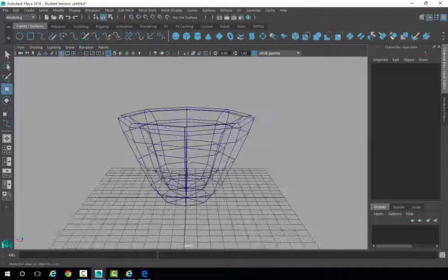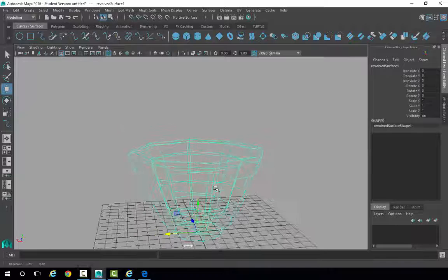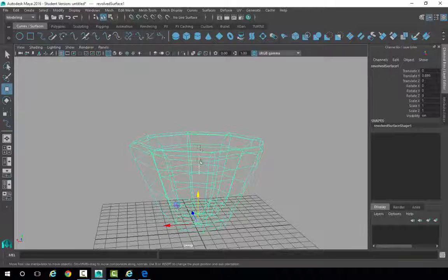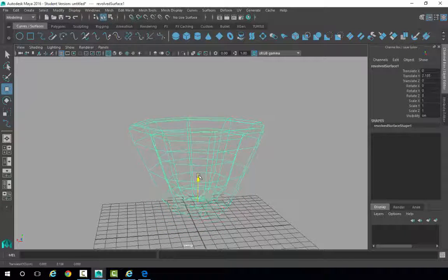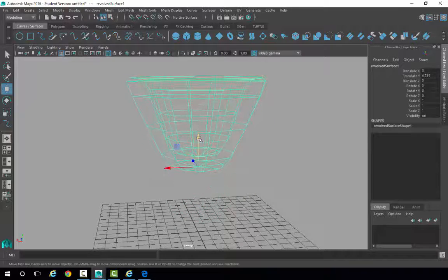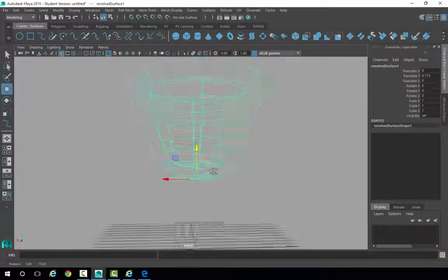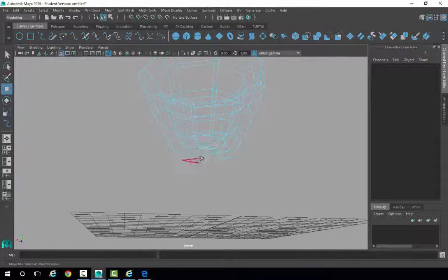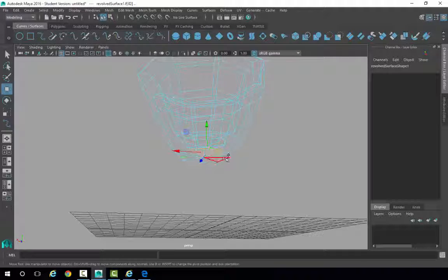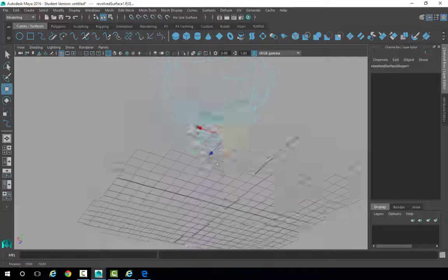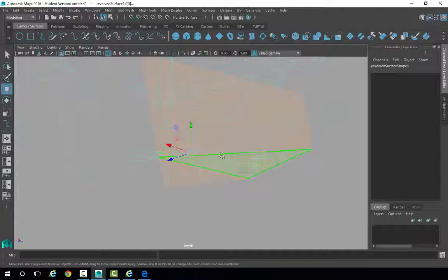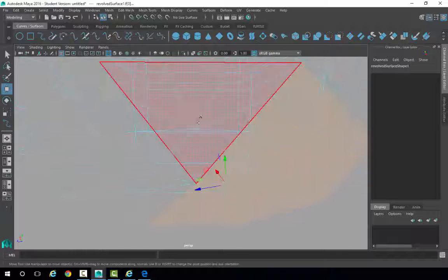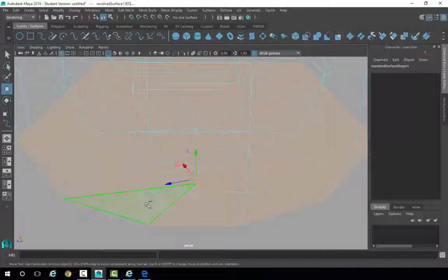So this is going to be a wine glass, remember, so I could have drawn the curve down to give us the wine glass, but what I wanted to show you was just a basic extrude. So I'm just going to move this up in here, and I'm just going to select those faces on the bottom. So that's these faces here. Just using the shift command, just zoom in. I zoomed in there using F for frame.